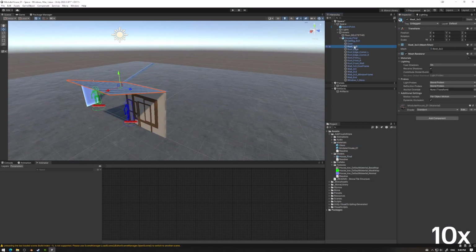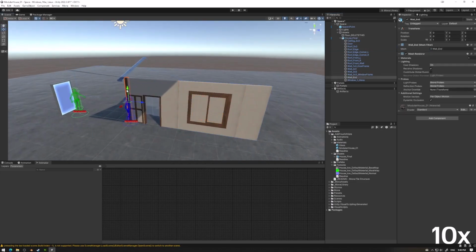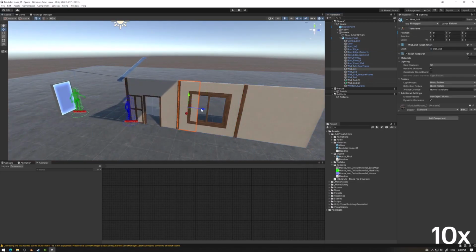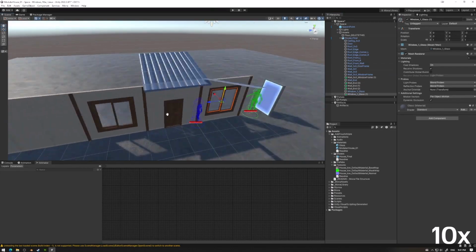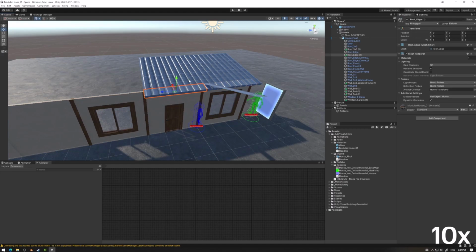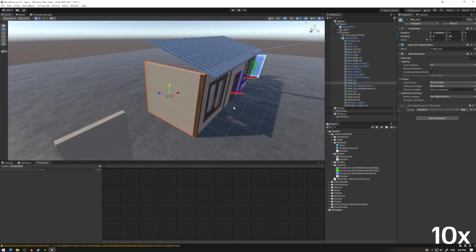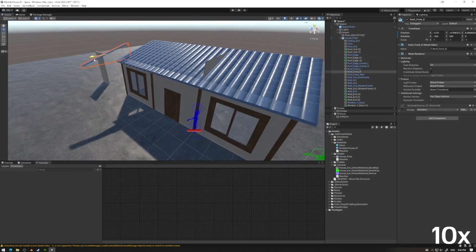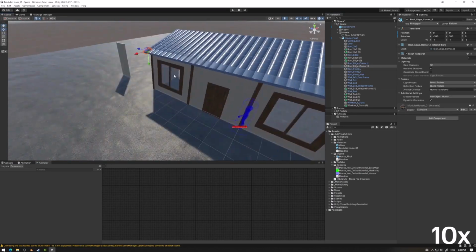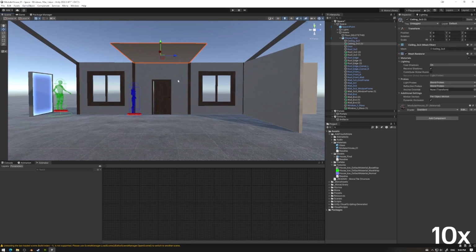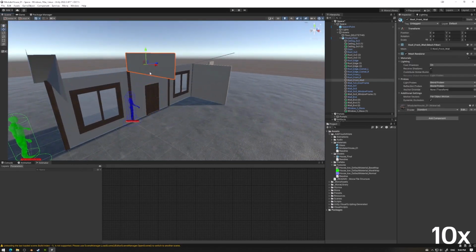If you want to test your GLBs in a Mona space, however, you will need to use a package to import the GLB, as this is not compatible natively in Unity. Two options for this include the Unity GLT Fast package or the UniVRM package. Both tools are covered in the documentation linked below. You'll see that I use a pillar to hide the lack of tiling on the wall, and jump back into Blender to make some tweaks to the assets as I go.